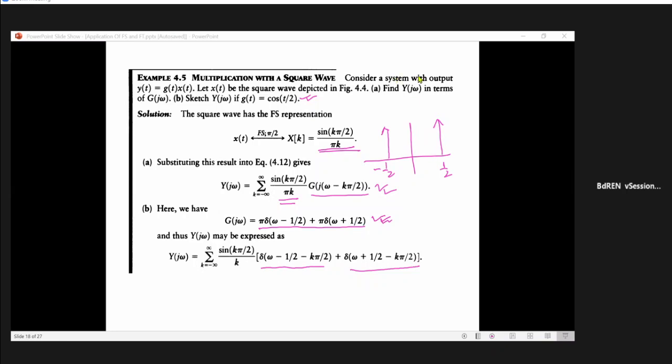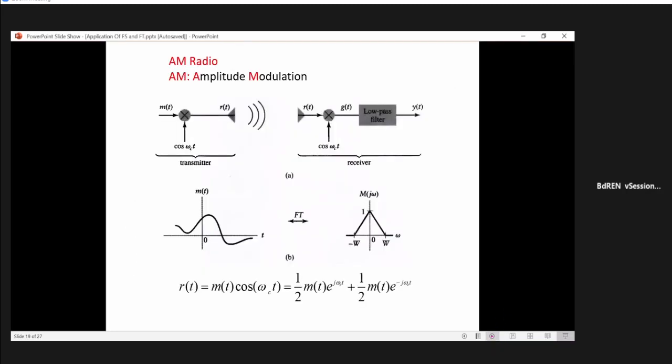One of the important applications of this property is in modulation. You see, in communication engineering, when we obtain a band limited signal, baseband communication may not be possible because of energy and other issues. For this reason, we have to modulate the signal with high frequency signals so that your spectrum will be shifted to higher frequency locations.